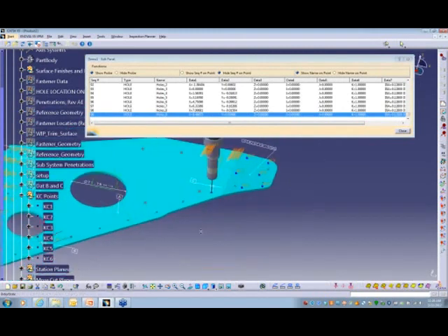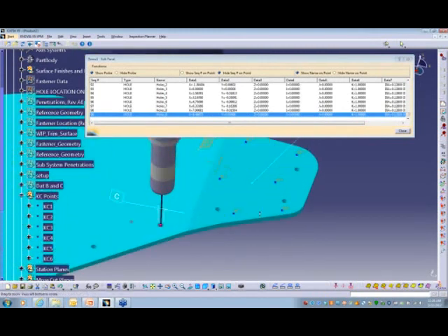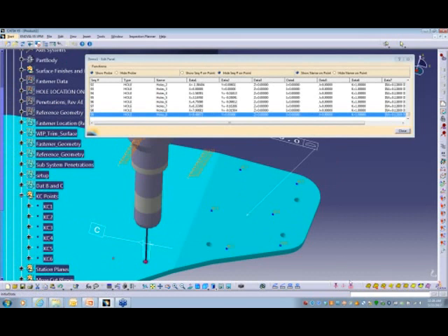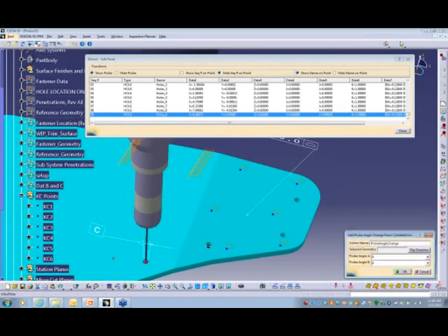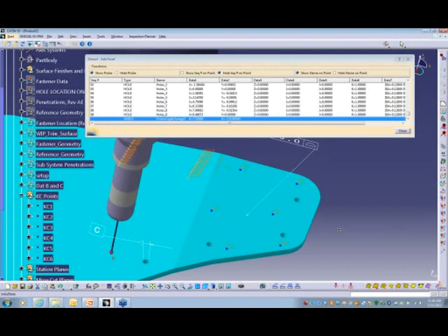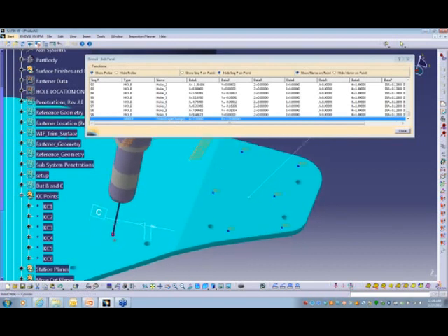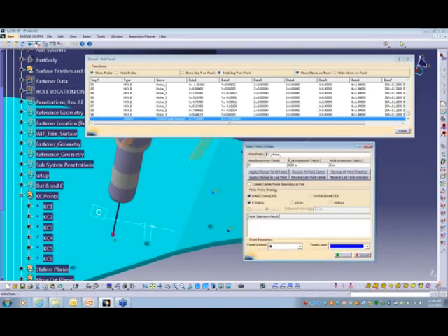And then if we want to measure 5-axis holes, we can come in here and say, I want to align the probe. So I know I'm going to lift 1 inch already above the hole, so I don't have to worry about that. I could pick this button, and I could pick the hole, and I can align my probe best to that hole, okay? And then I can pick this, and we'll keep the same here, we'll call it KC holes maybe.